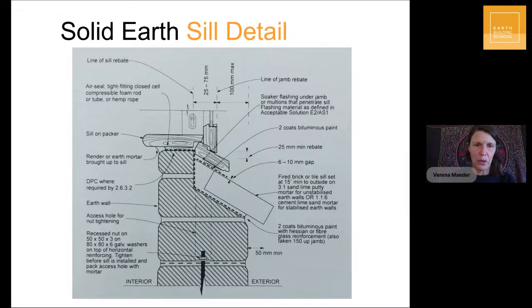Just going to show you a windowsill from the side now. So again, that's cut vertically through the window. You see the bottom, the wall below the window, and the sill. And you have to have a sill that sticks out over the face of the wall enough so that water can really drip off rather than flowing back onto the wall.